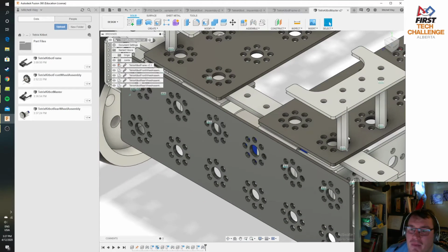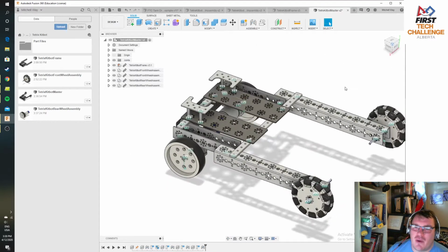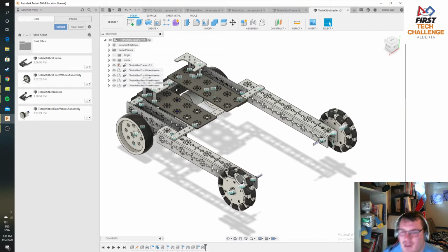That's awesome. Now, the next piece is that I've got this good frame, and I'm going to call this a good frame right now because this isn't really a great frame yet. It has a couple of problems that you should try to avoid when you build your particular robot. The very first of which is those long lever arms onto the front wheels. That's not necessarily a problem if you have something running across the front of the robot to brace it off. Otherwise, these will tend to move a lot because they are unsupported levers. There's a couple ways to fix this, including sliding them closer to your frame. It reduces your balance point on this robot, but there's nothing wrong with that necessarily.